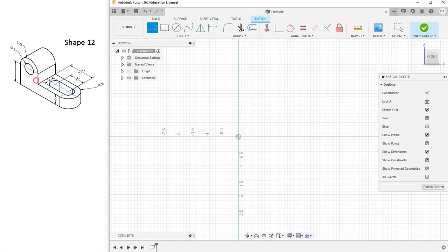But then what about this width right here on this part of the shape? Well, if you look, this arc on top of our shape has a radius of 0.5. And so let's think about that for a second. If this has a radius of 0.5, that means from the center to each edge is 0.5 inches. And so from this edge to the center is 0.5, and from this edge to the center is 0.5. That means this entire section of our part has a length of 1 inch, 0.5 plus 0.5.